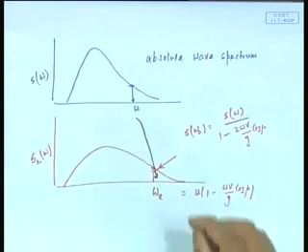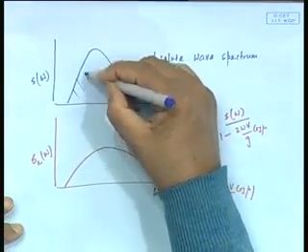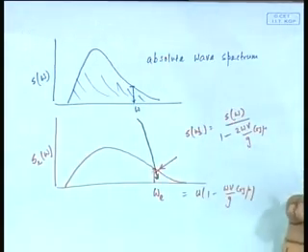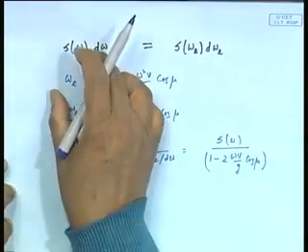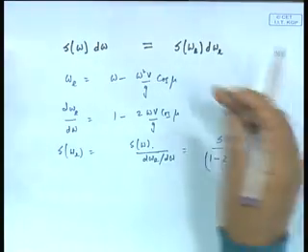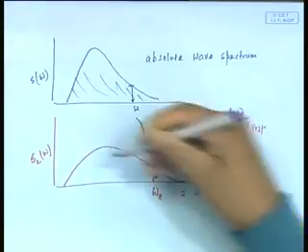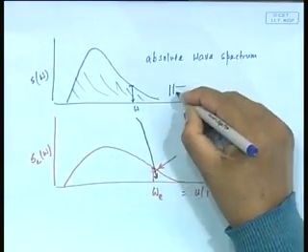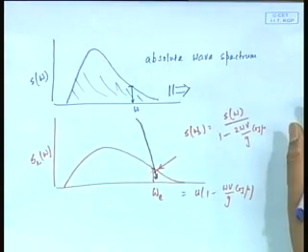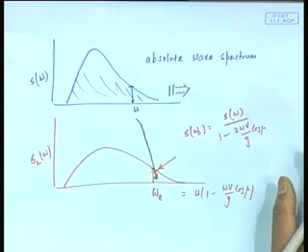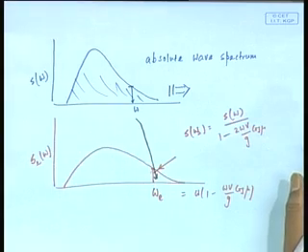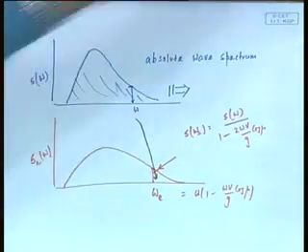So, it is something like, remember the area under this graph, net, what is the total area under this graph? The total energy of the waves, that must remain the same. Obviously that is true, because if you simply integrate this and this from 0 to infinity, the total energy remains the same because component energy is the same. So, there is no doubt on the area under that, and that is a fundamental principle, energy cannot change. But what has happened is interesting, that if I have a head sea, it is getting stretched this side and the top is coming down. It is like you are standing here and pulling it. So, there is a change in head waves. But look at the following wave, which is going to be very complicated in some sense. I will discuss that in a minute.